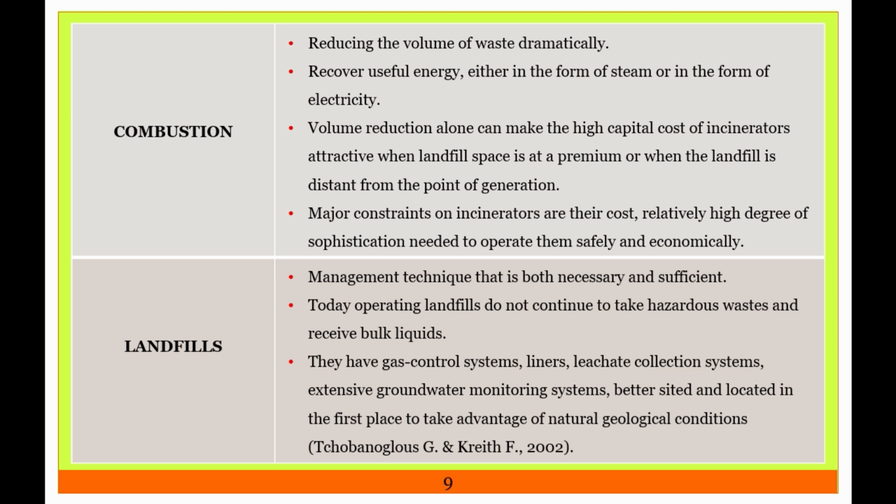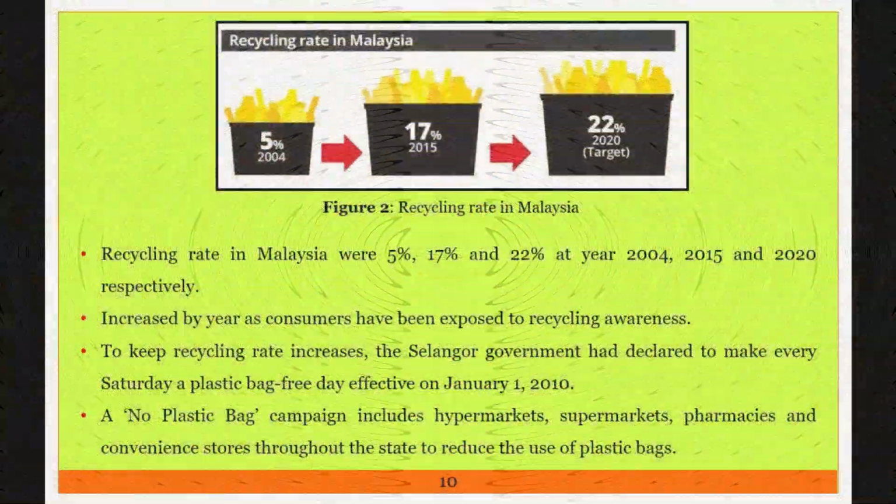And then the last is landfill. Landfill is a management technique that is both necessary and sufficient. Today, operating landfills do not continue to take hazardous waste and receive bulk liquids. They have gas control systems, liner leachate collection systems, extensive groundwater monitoring systems, and are better sited and located in the first place to take advantage of natural geological conditions.